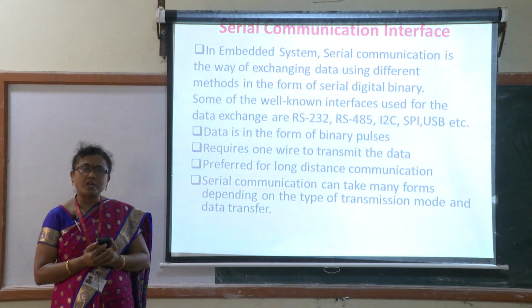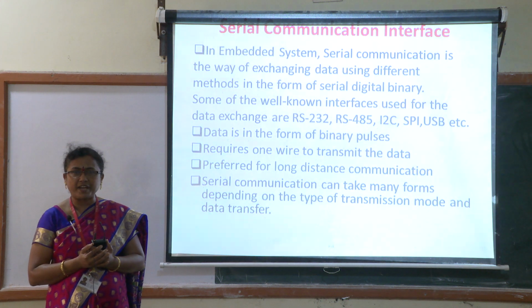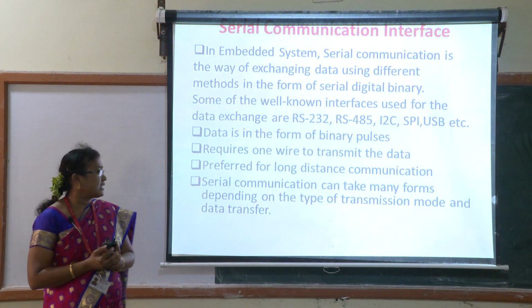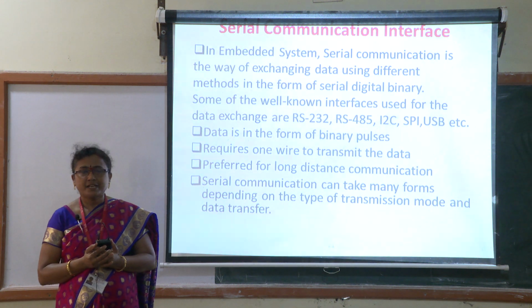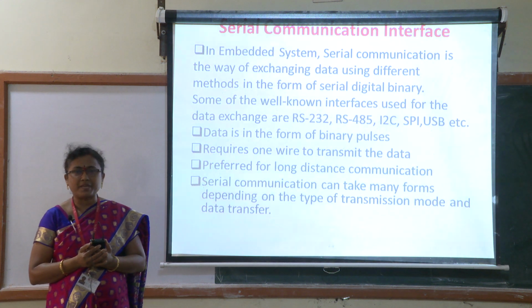So we will move on to the RS-485 standard. Under RS-485, I can connect a maximum of 32 devices. Among these 32 devices, one node may be a master and the other nodes may be slaves.